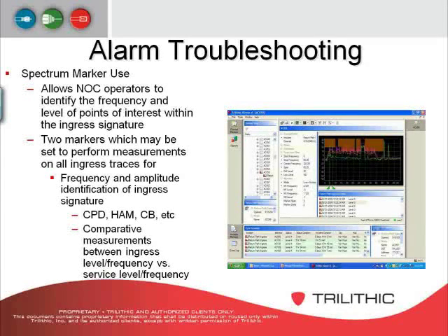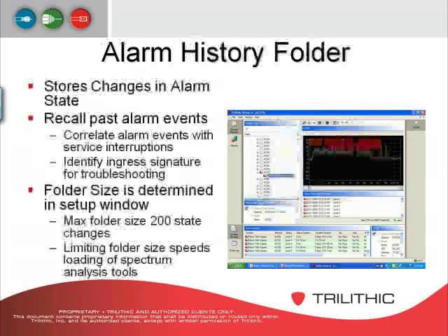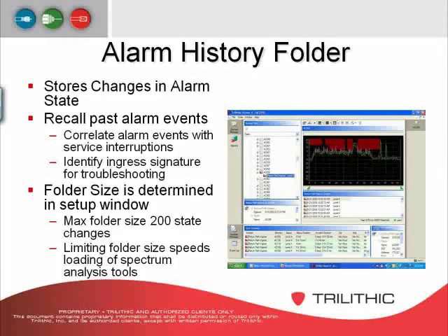A comparative measurement between ingress level or frequency versus the service level or frequency. So it's what's happening right now as opposed to what did happen. So it stores changes in alarm states, recalls past alarm events, correlates alarm events with service interruptions, and identifies ingress signatures for troubleshooting.